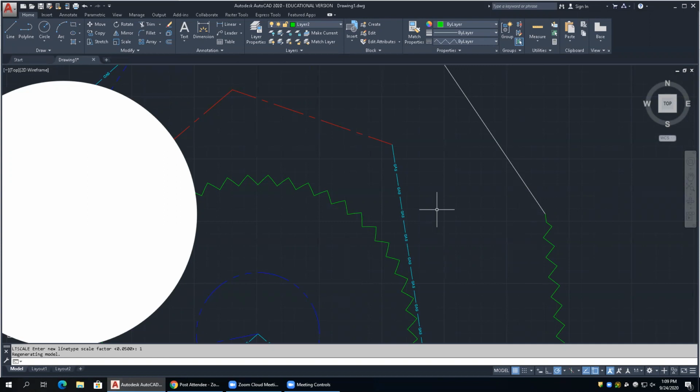Here's what most people do. And again, I'm not going to say everybody does this because people play with them they shouldn't. Line type scale factors for the objects should typically be set to 1. So then all you're doing is just adjusting the global. 5 times 1 is 5, 6 times 1 is 6. So it always stays whatever you're doing globally. But if you mess with the scale factor on the object, then you're going to change it up.